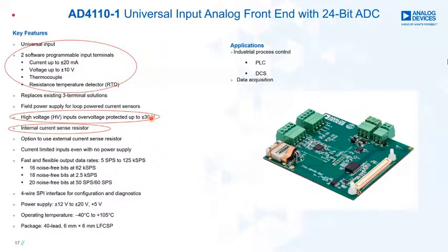Usually we need resistors with 0.1% accuracy. And you can imagine if you have 5 or 6 or 10 channels of IO points, then you have to procure that many of them, which can increase the system cost significantly. We have used precision resistors inside the chipset to ease your system design.